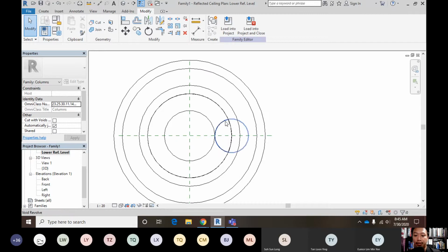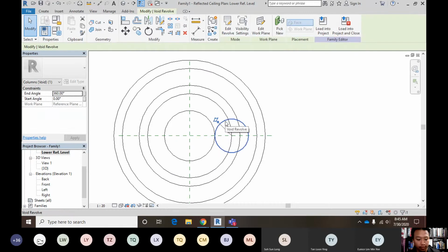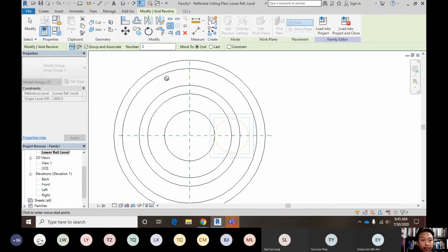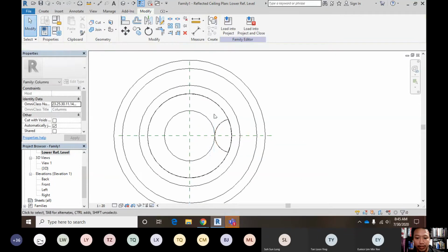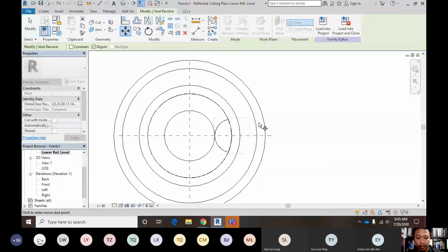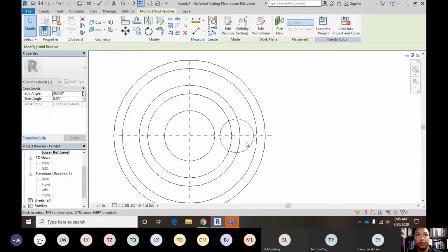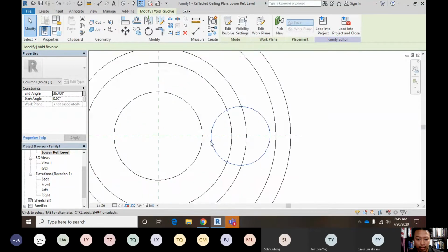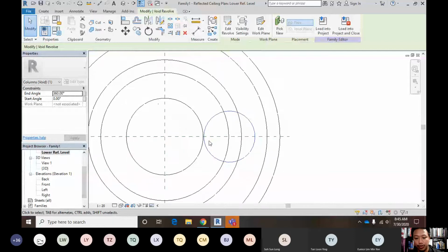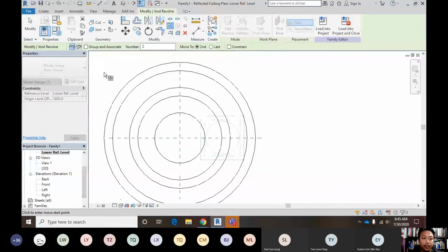Okay, then what I would do is I will array polar group. Okay, array polar. First I need to disjoint it so that it doesn't really attach to anything. So I move it, disjoint. That's how we disjoint. Just move it back to the place. Don't undo because it's already disjoint. Okay, and you can array.